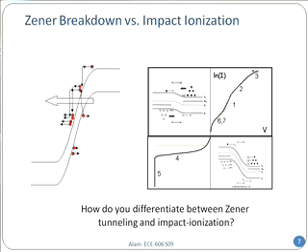So we have actually gone through all these DC characteristics. Region 1, purely diffusion. Region 2, what is that? Half the slope, ambipolar transport, because electron and hole were so much, they essentially become equal to each other. So the n_i squared divided by N_A picked up a square root. Similarly, region 3, what is it? Huge injection, so that there was a huge resistance drop in the bulk region itself.